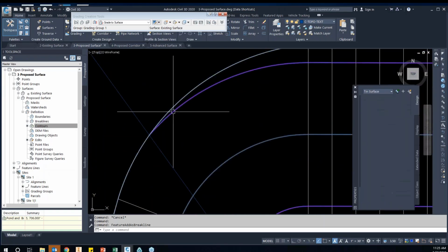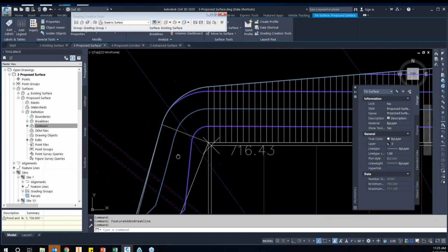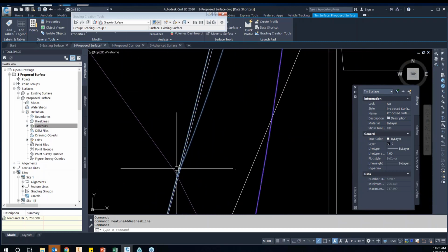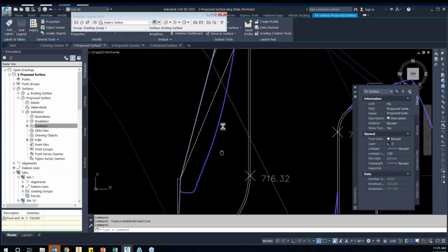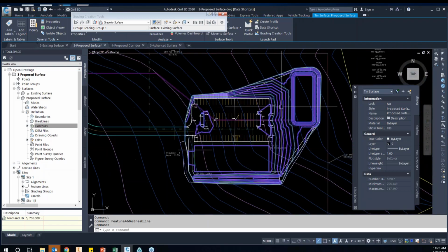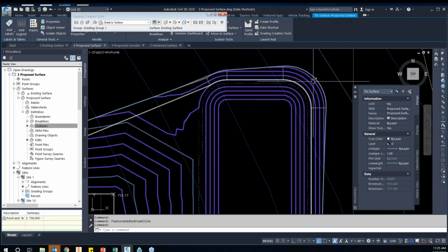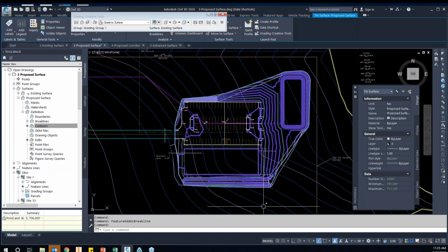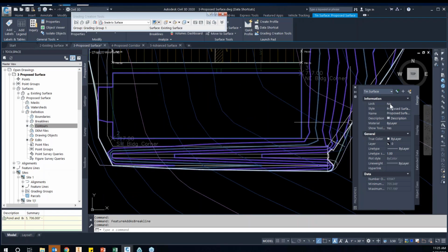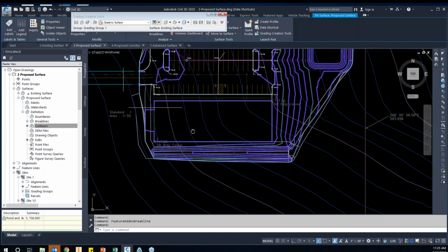And if you look at the contours, you'll see that our contours are tying in right back into the existing contours. Okay. So they hit the existing surface pretty accurately outside of our surface here. All right. So we've got a nice clean grading situation from our pond using polylines. All right, we use the grading object to get a nice clean tie-in. All right. And then we used feature lines back here on the ditch, okay, to give ourselves a nice clean ditch back here. So that grading looks pretty nice and clean.